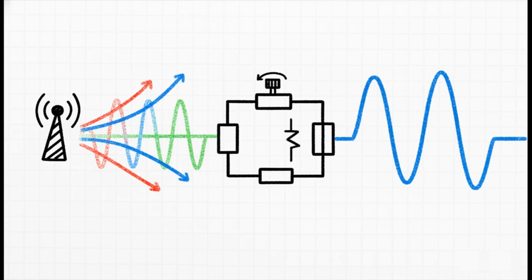A radio receiver uses an RLC circuit as its tuner. When you turn that dial, what you're actually doing is changing the capacitor. This changes the circuit's resonant frequency. When you get that frequency to match the carrier frequency of a station you want to listen to, the current for that signal is maximized, so it gets amplified, while all the other station signals are basically ignored.